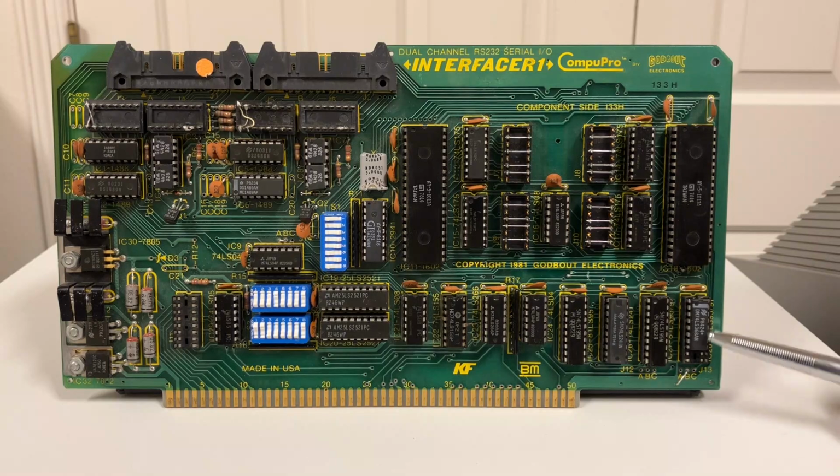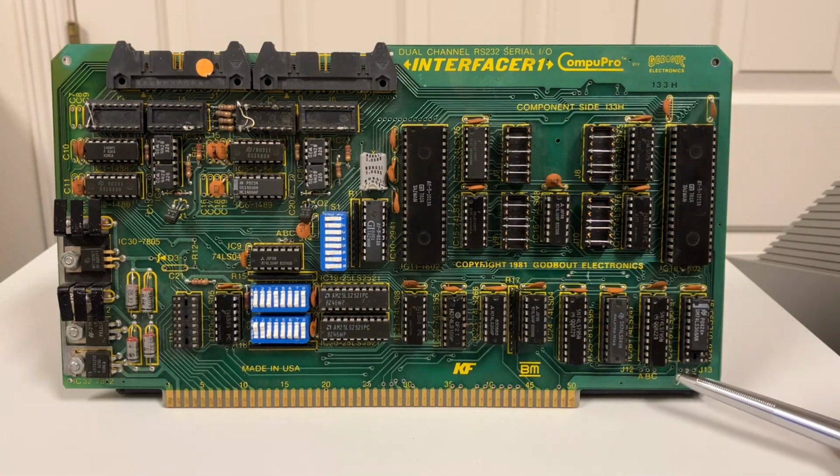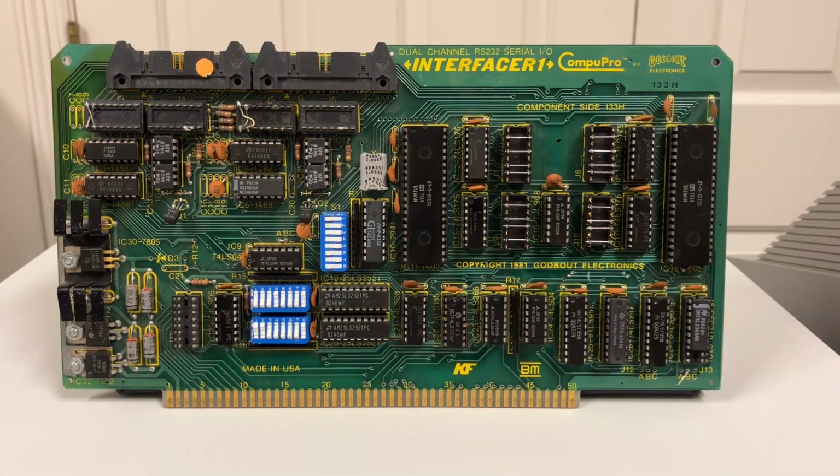The first 3 are the same, the last 3 are the same. That covers the bits we're going to use. This upper pin in the corner, pin 16 or 20, that is VCC. The only thing we need to hook up still is pin 8 there for ground. Pin 8 is driven by this jumper ABC here. So I just connected that jumper to ground, and at that point pin 8 is grounded just like we need. So this works just fine.